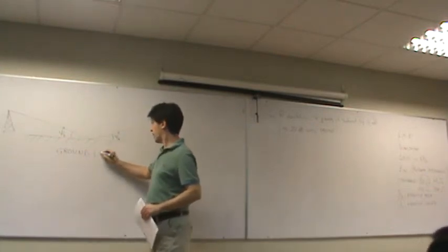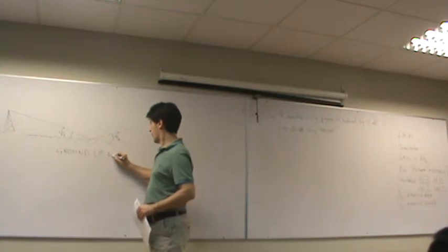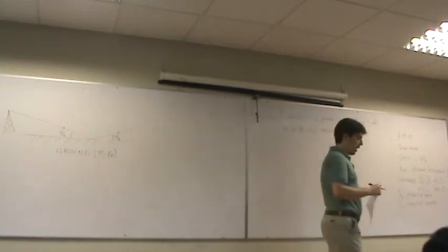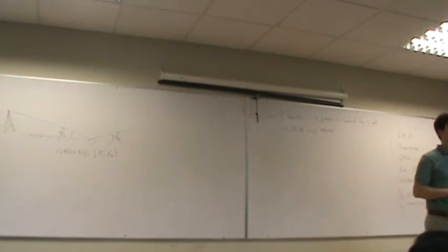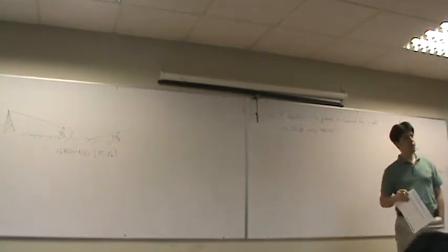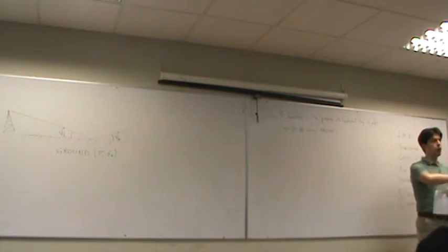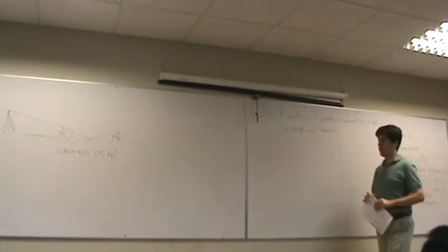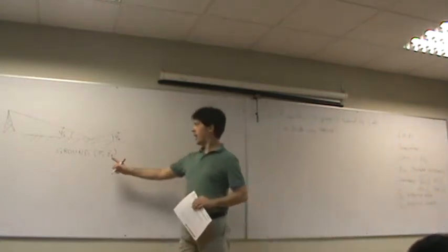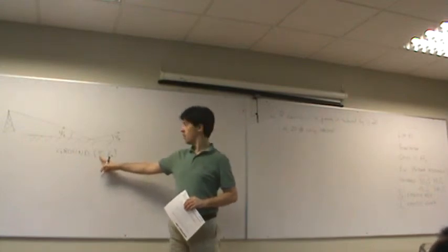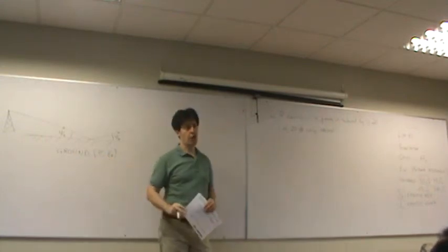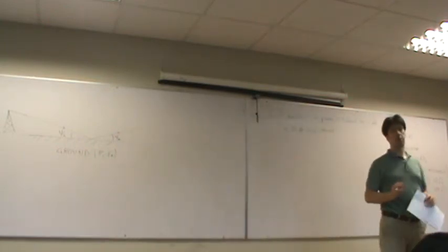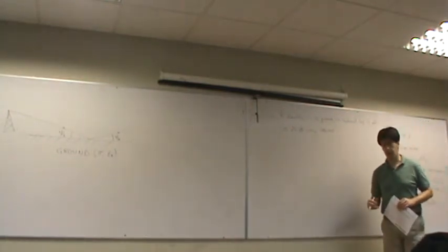Now, first of all, the properties of the ground. As I said, with ground I mean also water, salt water, fresh water, anything that is a flat horizontal surface. The properties of the ground are described by the conductivity and dielectric constant. And those two parameters are highly variable depending on the kind of ground that you are dealing with.